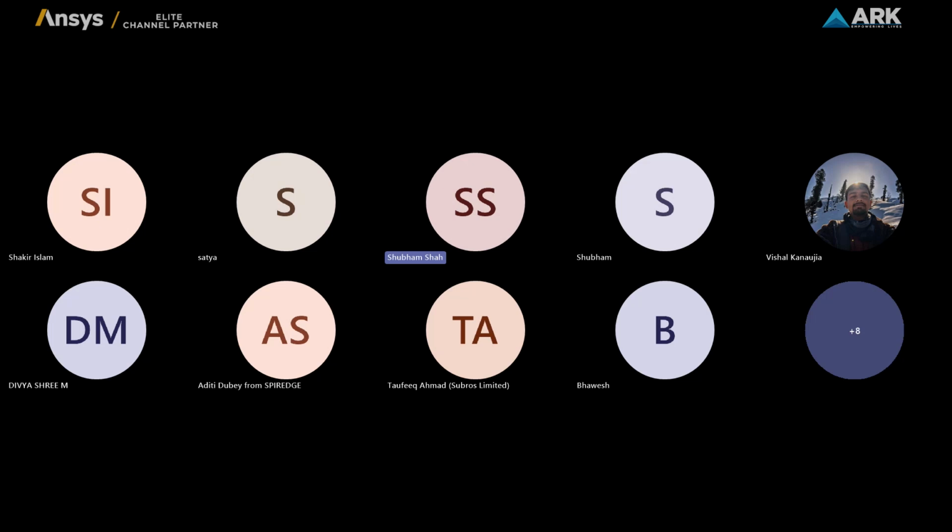Or let's say a heat sink is there, and the fins of the heat sink are placed at a very small distance, 1 mm or 2 mm, depending upon the type of heat fins. The tool will automatically refine the necessary regions where the gaps between two objects are small. When it sees there is no object and the area is open, it will automatically create a coarser mesh there. That is basically automated meshing. So even if your object is complex, it's easier compared to other tools to perform the mesh in Ansys Icepak meshing.